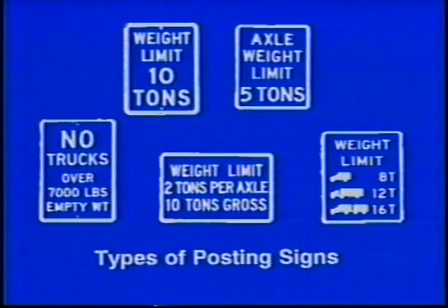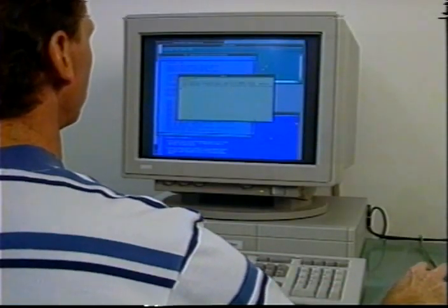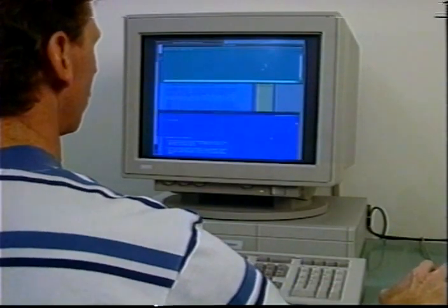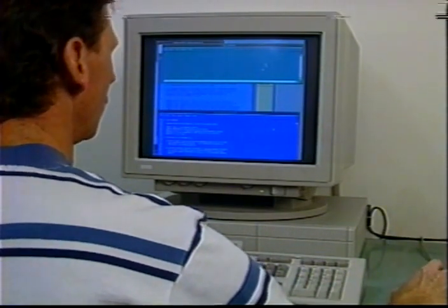Standard procedures for bridge posting vary. Most states and local governments use gross weight limit word message signs. The posting may describe different limits for different truck configurations. Before a bridge is posted, engineers must determine its safe load capacity. The safe load capacity includes a factor of safety. In this way, load posting helps prevent structural damage.